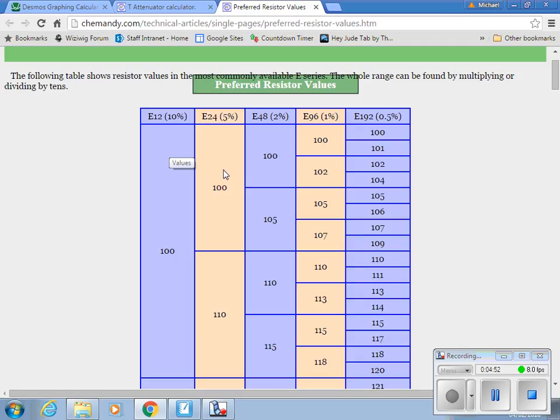Now, at the college, Chris buys 5% resistors, plus or minus 5%, but he only buys every other one in the range. His view is that we don't need every value in the 5% range, and largely they're the budget worst resistors available, if you like. Not many people bother with 10% these days. So he gets the values that are in the 10% range, but he buys 5% resistors.